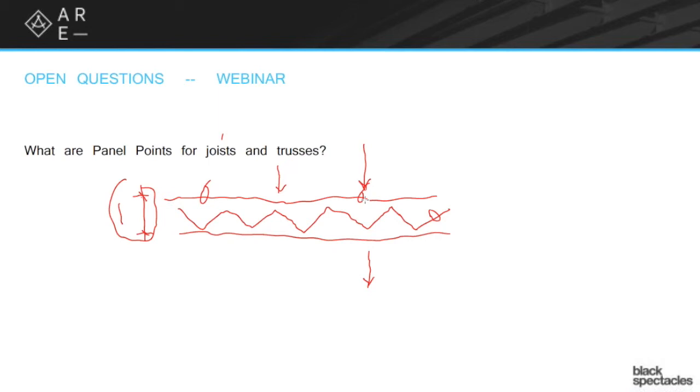So trusses are an incredibly simple idea, but you have to use them carefully because if you load them incorrectly, they will fail dramatically. Now, obviously, there's a lot of different versions of trusses. There's sloping trusses. There's scissor trusses. There's a whole series of different types of trusses. There's a lot of online material showing you different examples. The concept holds true no matter what. You're always loading at the point where those loads can be spread to the other members and not where any one individual portion is taking the whole load.